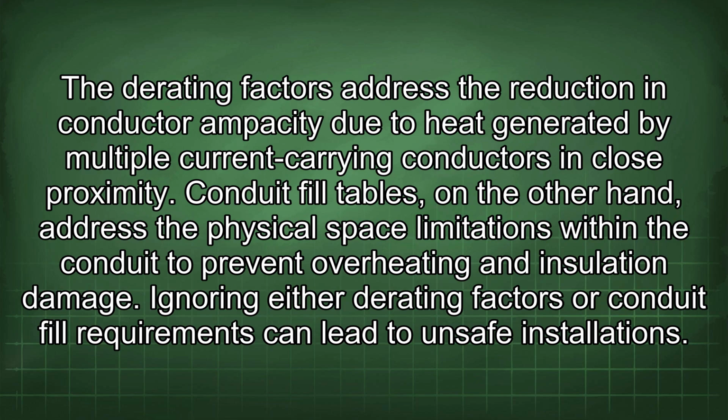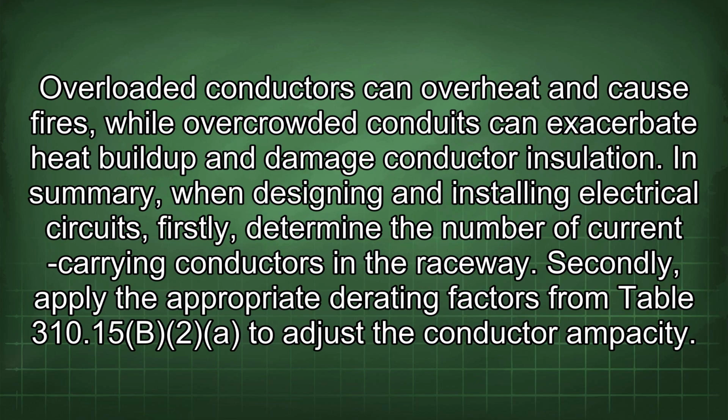Conduit fill tables, on the other hand, address the physical space limitations within the conduit to prevent overheating and insulation damage. Ignoring either derating factors or conduit fill requirements can lead to unsafe installations. Overloaded conductors can overheat and cause fires, while overcrowded conduits can exacerbate heat buildup and damage conductor insulation.